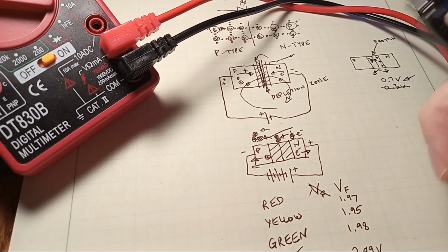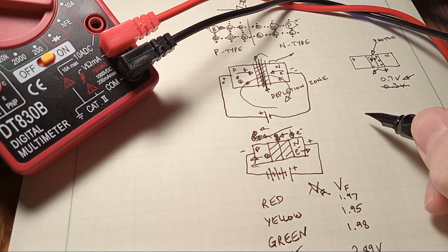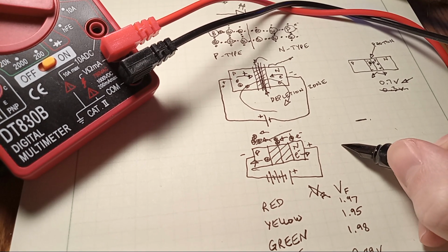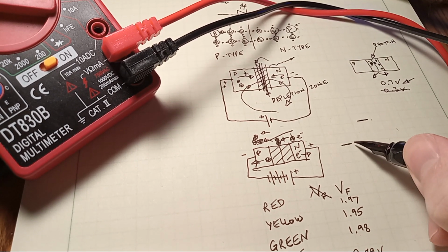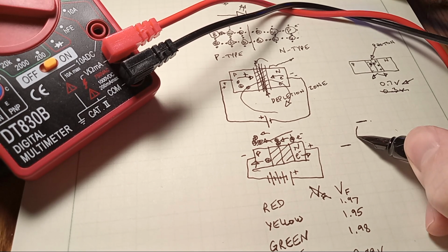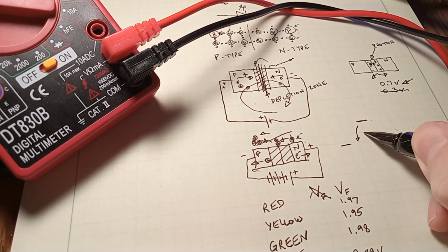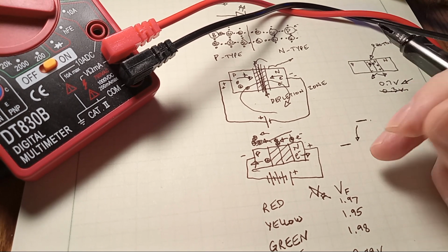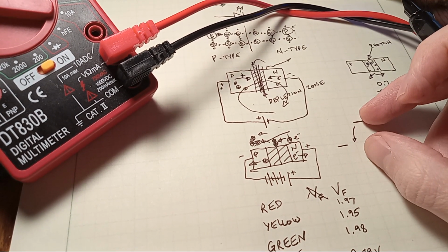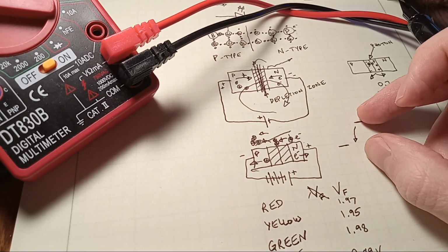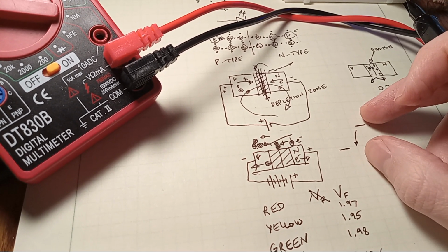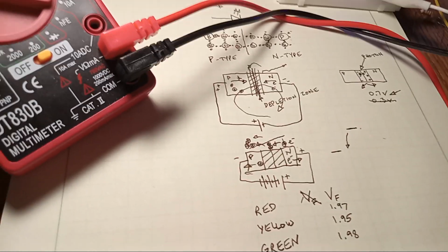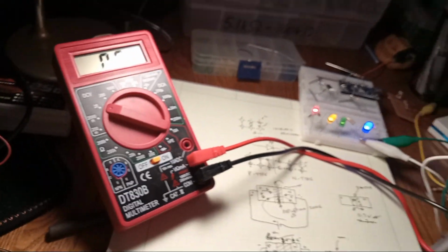Which material you use affects the band gap voltage, that is the difference between an electron that's in the conduction band versus the valence band, which is where the electron falls at where the junction meets. That distance controls how much energy is imparted to the photon. I might come back to this description more later. I feel like I haven't quite done it justice.